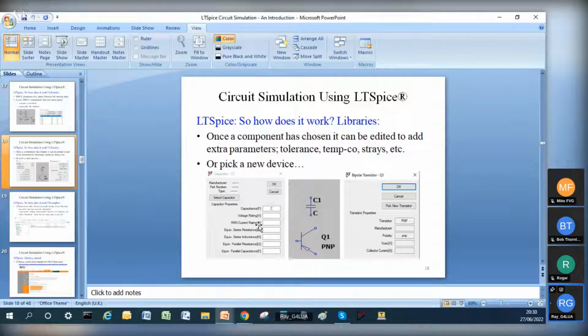That's the capacitor. In the capacitor we can add the loss component, because an ideal capacitor has no losses, whereas an electrolytic capacitor has some resistive losses. Some of the ceramic capacitors will have a phase component, particularly RF capacitors will have a dielectric loss, which you can put in and simulate more of a real world component.